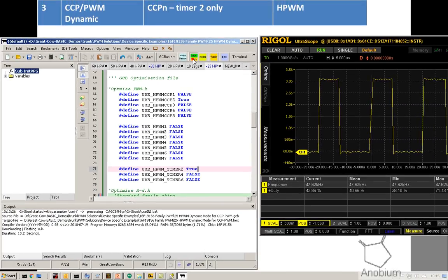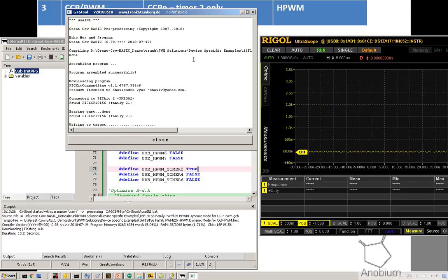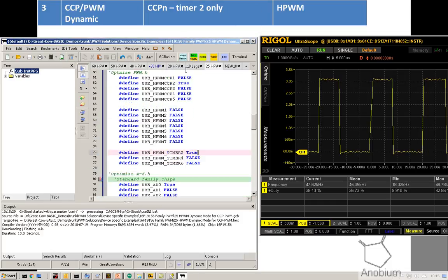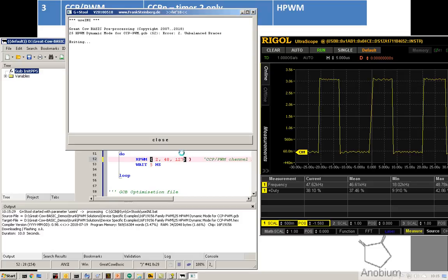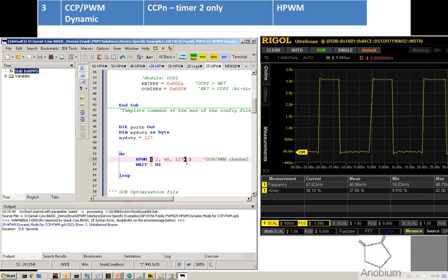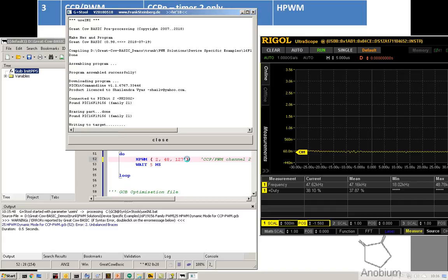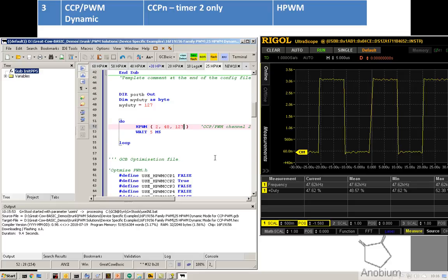All right, okay. So currently we're at 826 words, and it does ramble inside of there. It's using 826 because we're doing ADC as well. Okay, all right. 569. If I turn the ADC off, I guarantee if I just put a static value there of 127, which is, ooh, oh yeah, unbalanced braces. You've seen that before, hey? So this is just doing now a 50%. There we go. And it's now using 519. So it's coming down and down and down. So you can optimize the code.